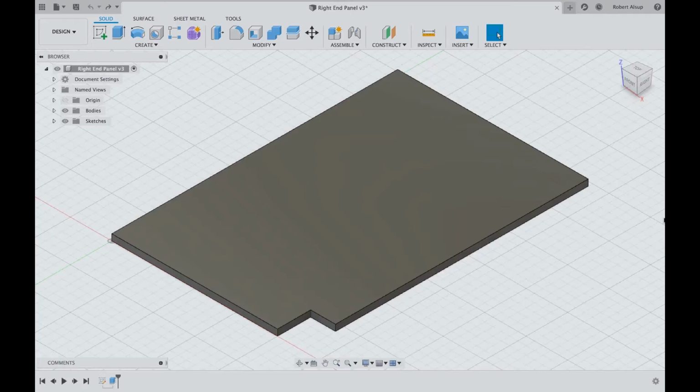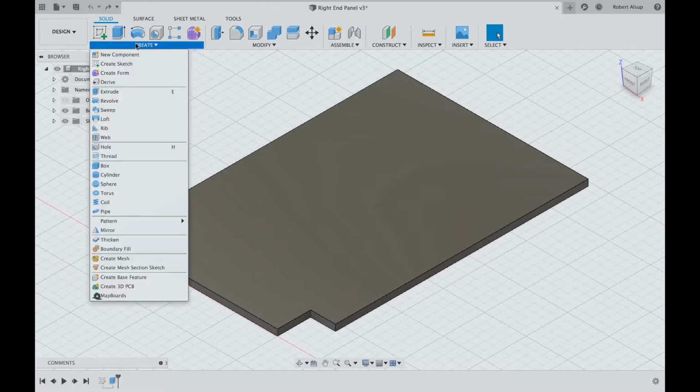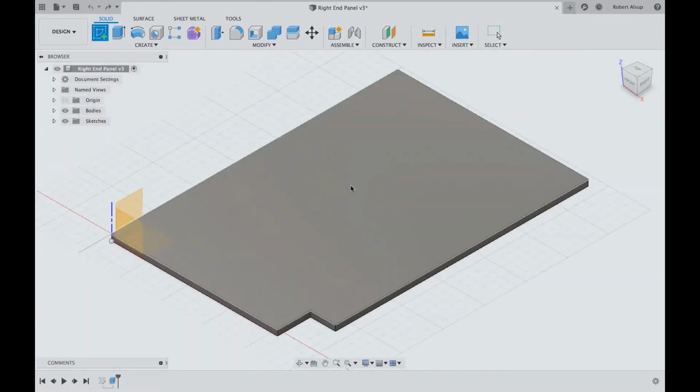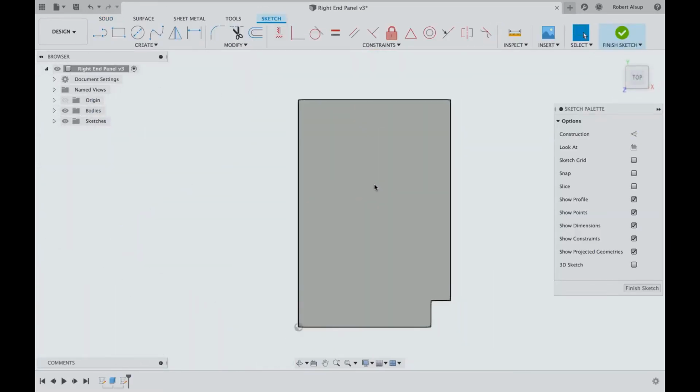Well, our cabinet part needs joinery. So think about, how would I do that in VCarve Pro? Well, I'd probably just draw some rectangles where the joints are and get them positioned, and then they would get toolpathed. Well, let's approach that the same way. So let's create a sketch that has the joints on it. So we start by create sketch, and we'll pick that surface and we'll bring it out a little bit. I have better luck drawing out here in the canvas than moving it over.